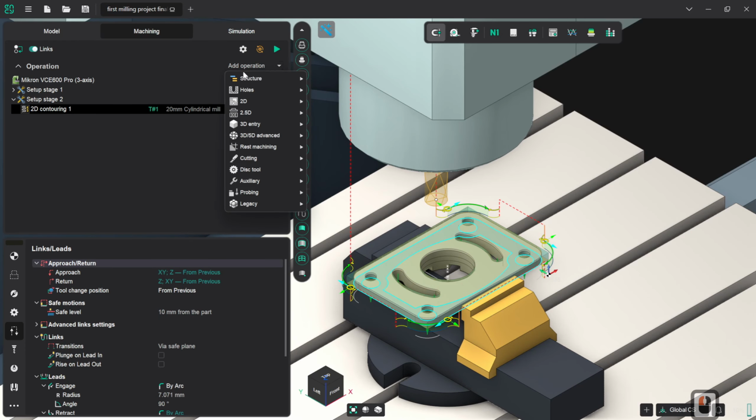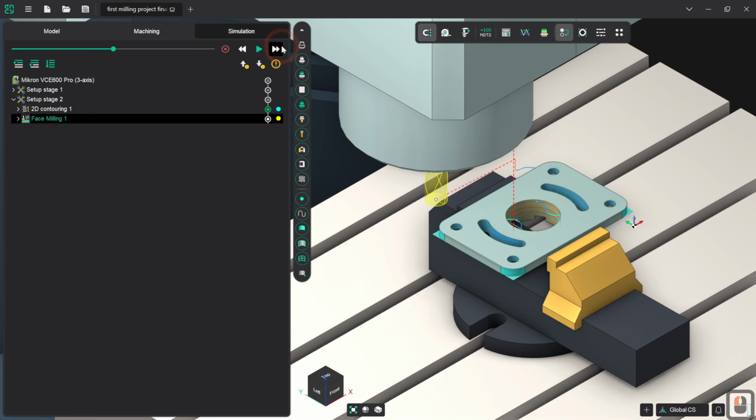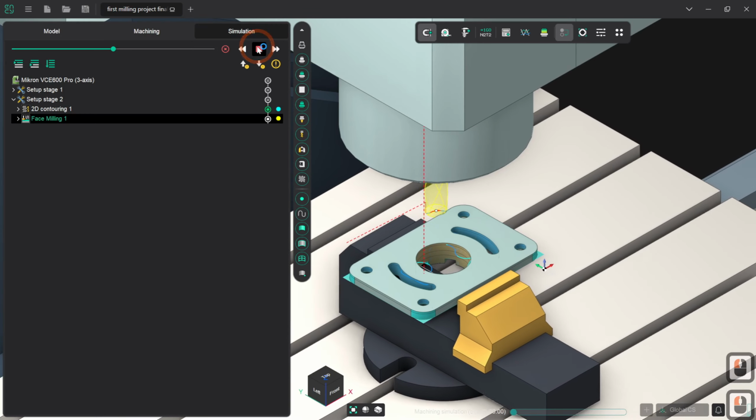We've got the correct kind of tool. Everything else about this we know to be good. It's the spiral with a 15mm step over. It's exactly the same as we had our first setup be. So I'm going to click on generate toolpath now, and we can see that's exactly the kind of toolpath we'd expect. We're going to simulate it very quickly just to make doubly sure. And there are no surprises here at all, which is something that I always like to hear, especially when setting up a machining job. Surprises are not your friend.